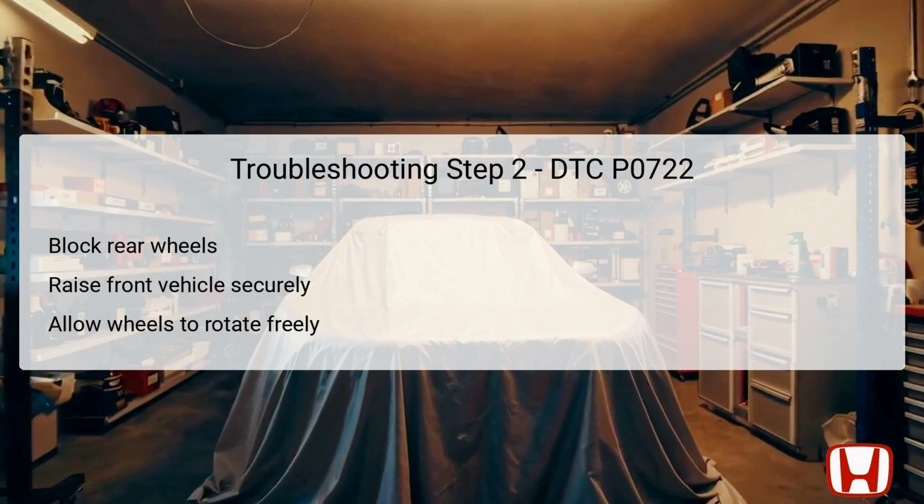In the second step, ensure the rear wheels are blocked to prevent any unwanted movement during testing. After securing the rear wheels, lift the front of the vehicle, making sure the vehicle is adequately supported, either with jack stands or a lift. This precaution is pivotal for safety during the diagnostic process.